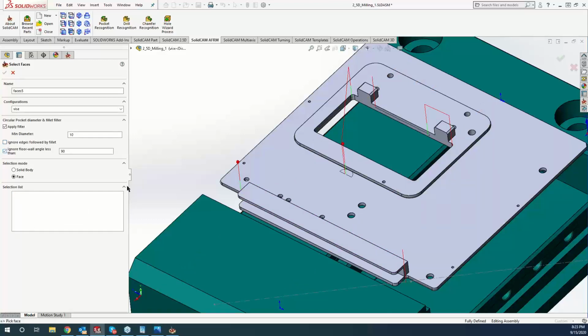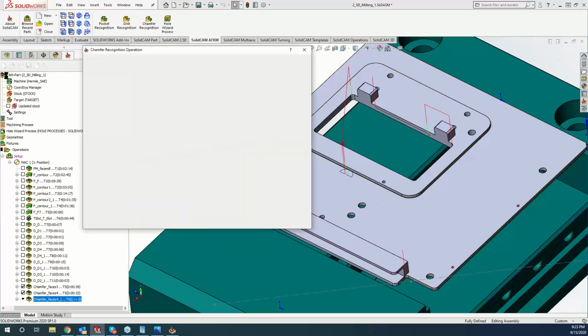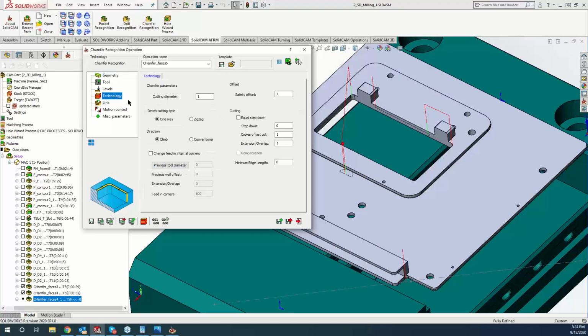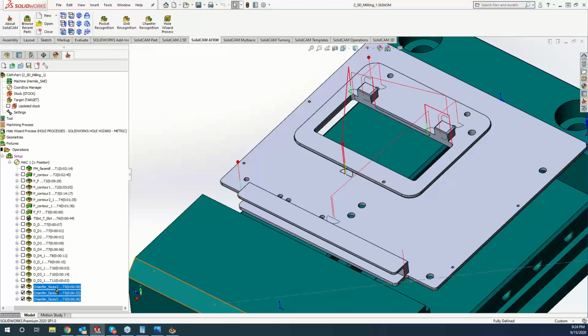We're going to ignore the 45. So this face I want to chamfer along with this face, along with this face. And I can change this one up to maybe I want a 0.3 millimeter edge break or chamfer on there. So now, just by doing quick saving copies, I was able to tell it what faces I would like to chamfer. So this face, I wanted a 1 millimeter chamfer. This face down here, I wanted a 0.5, and then these three top faces, I wanted a 0.3.